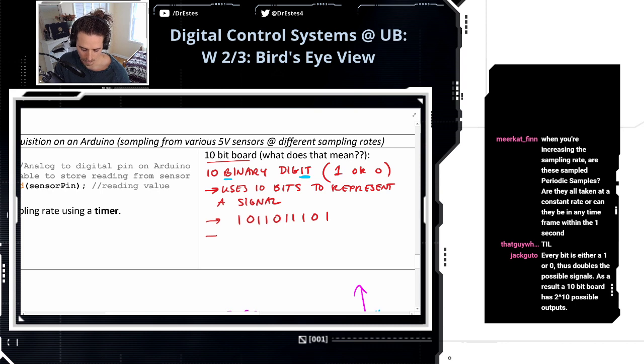And if you think about this, there's only 2 to the 10, which is 1024 combinations that are possible, because we're only working with binary digits, zeros or ones. And if I only have 10 bits to use to encode some value that comes in, a voltage, there's only 1024 levels or combinations that I can possibly attribute to.